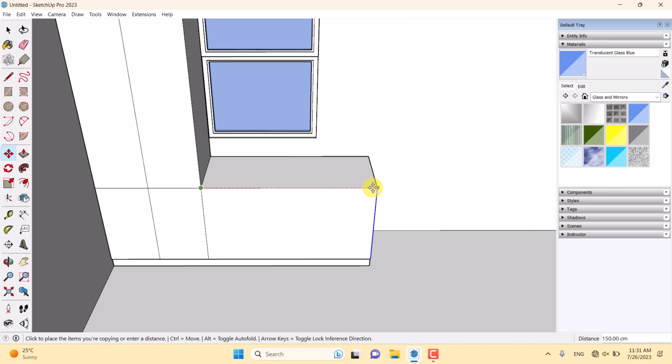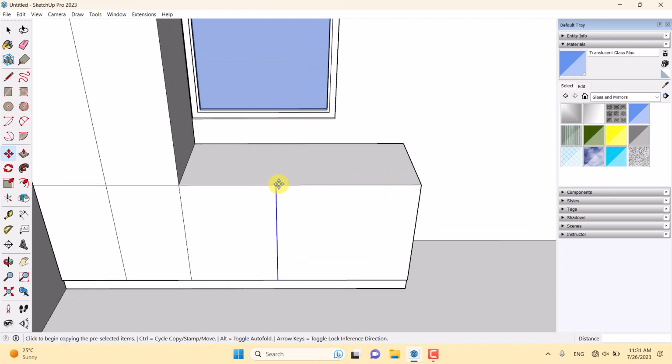So the main height is about 80 centimeter. I can use 26 centimeter. And now I'm going to take some multi copies of it. So listen carefully to this place. I want 2 copies of it. So I'm going to type 2 on my keyboard and X on my keyboard and press enter. As you can see, we take some copies, very useful in SketchUp. So now I'm going to click on it and convert it to a group in here.